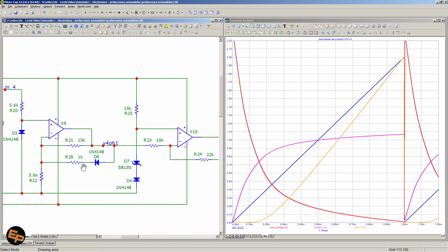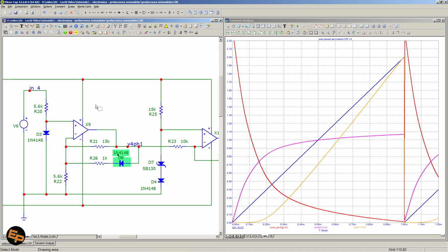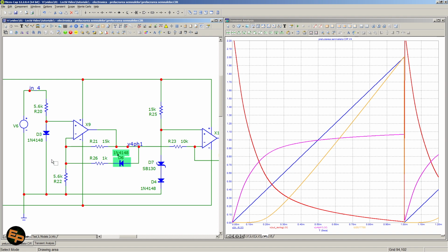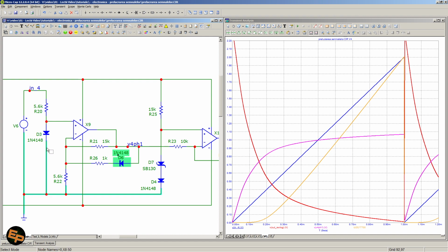We have a more complex circuit that has two operational amplifiers. Well, it has two operational amplifiers because I wanted to invert the signal at the end. But anyway, we have a completely different principle of working here. We have the input signal that is fed directly through a resistor to a rectifying diode, so that the input signal directly generates voltage across this diode.